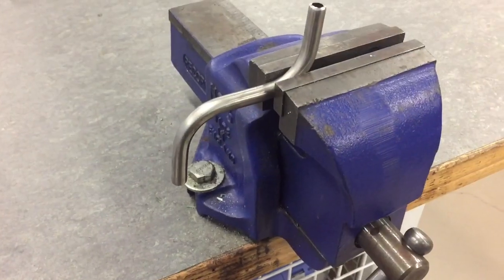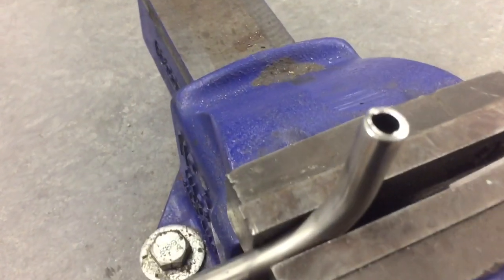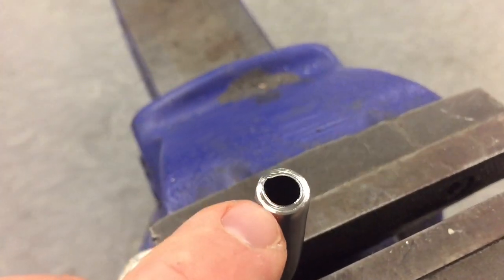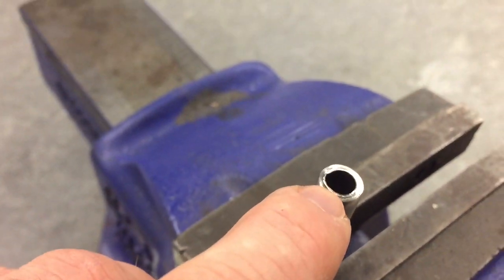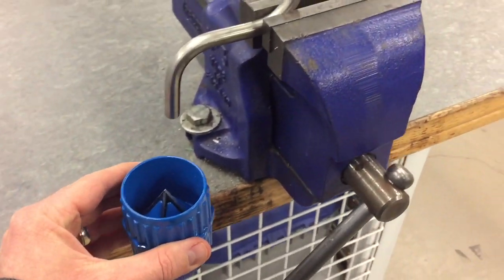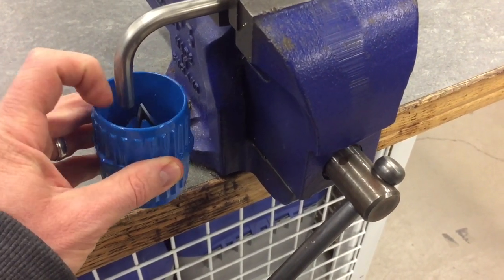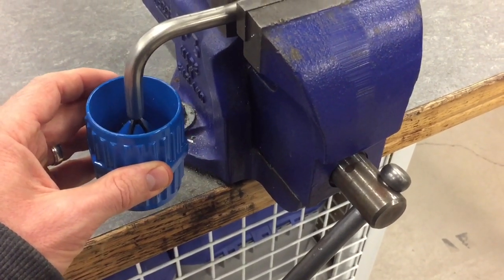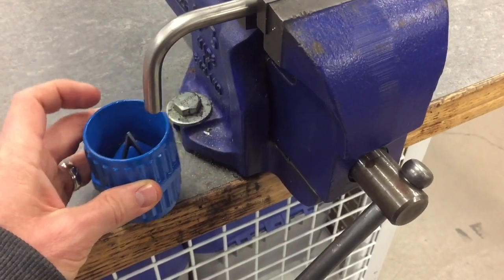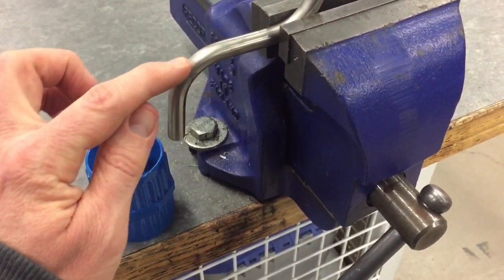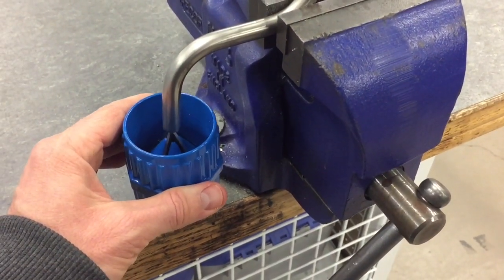Alright, so after we've cut the tubing, you can notice here there's some sharp edges, what they call burrs. So what we want to use is a deburring tool right here to remove those burrs. And this deburring tool we always use from the bottom here, because this cup collects the burrs as they're knocked off. That way they don't collect inside the tubing and plug off small ports and instruments.